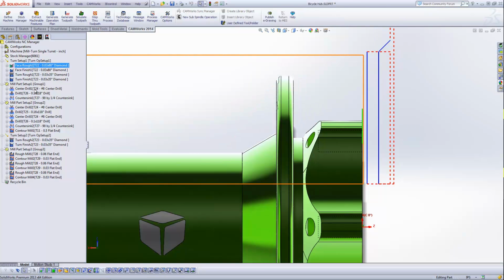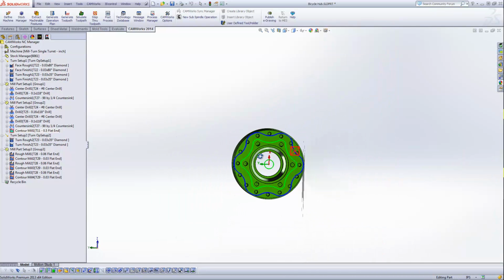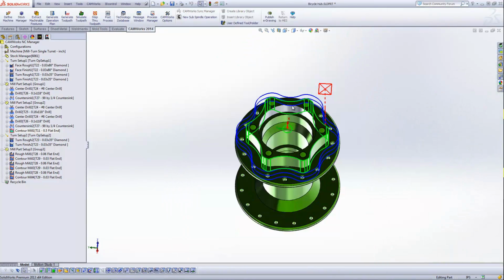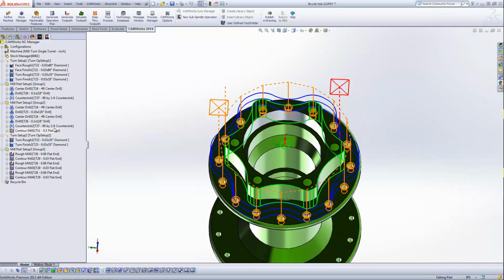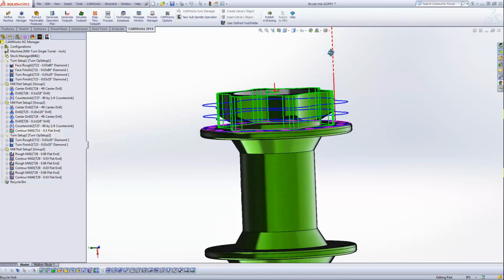Looking at a mill toolpath, here's that boss. Right? So we can kind of see how that's working. It's using a 1/2-inch flat end mill. No lead-ins or lead-outs right now, and it's taken 3 depths of cut.